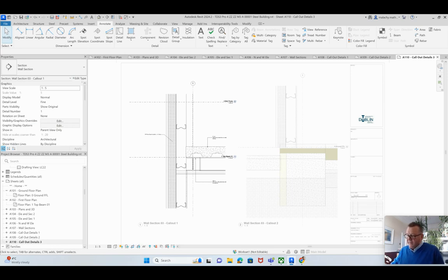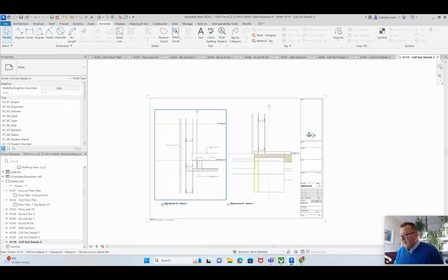If you wanted to individually note each one of those, that's the process: go into each individual material, fill out the description, load the material tag into your project, and then you'll be able to go bang, bang, bang. You'll be able to take each one of those and note them accordingly. And when you get down to the 1:5 detail, that's where the material tag kind of comes into its own. All right. So I will just deactivate that view.